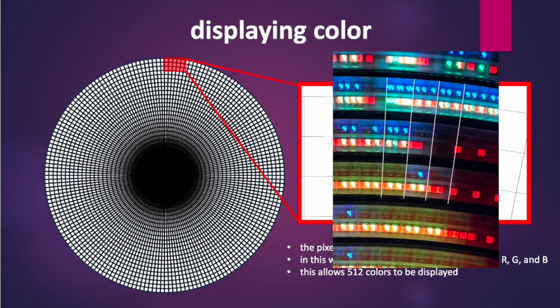Here's a photo of a real image section. The red and green LEDs are next to each other, while the blue LEDs are radially offset. The white lines mark the transition between the macro pixels, and you can see the subpixels. Within the macro pixels, the LEDs are only switched on for a certain time.